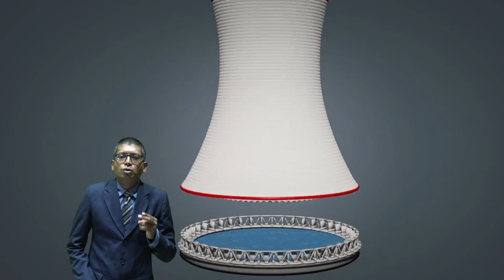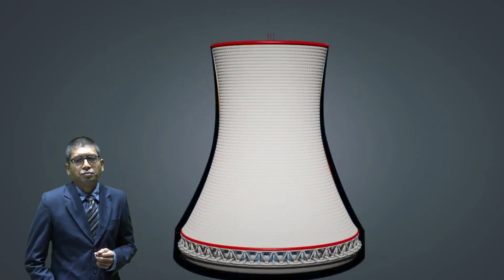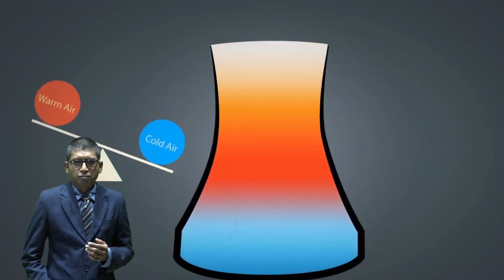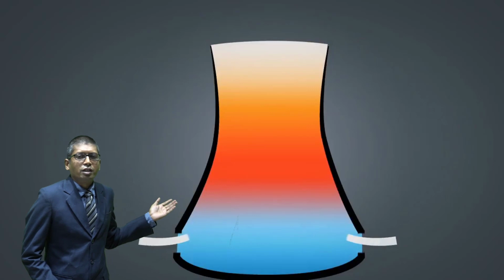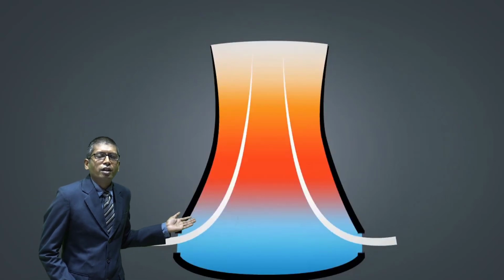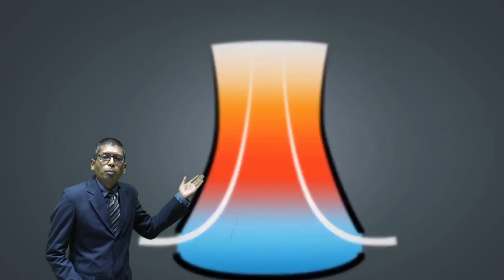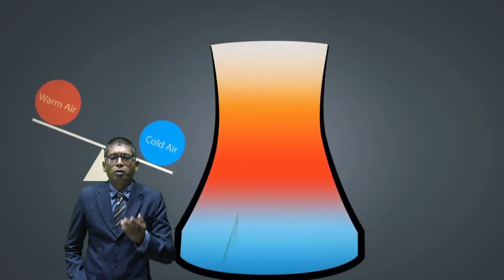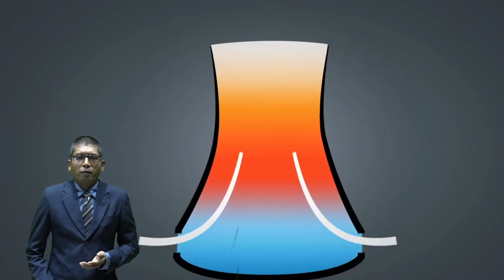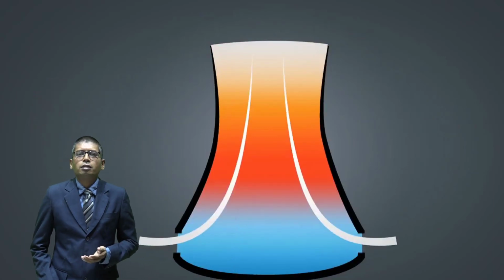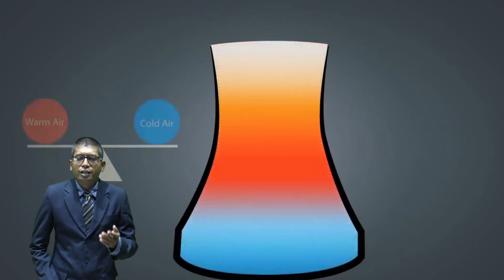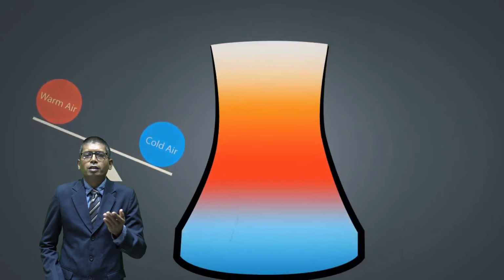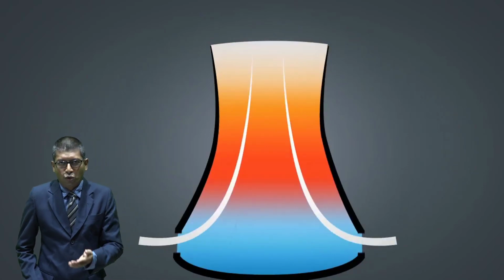During the process, 2% of the water evaporates. This cooling tower works on the principle of natural convection. Due to the difference in the density, the warm air, which has lesser density compared to the cold air, goes upward and escapes to the atmosphere at the opening at the top of the tower. We all know that when the air density decreases, it goes upward. Due to this, the cold air flows by natural convection, and the hot water is cooled.